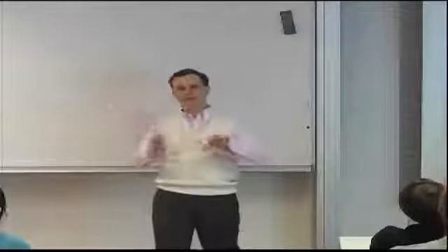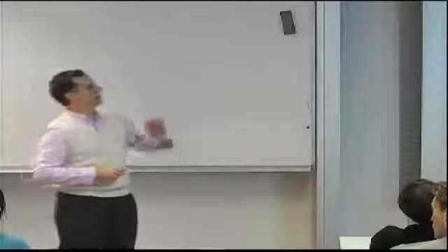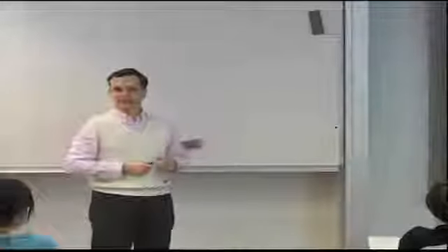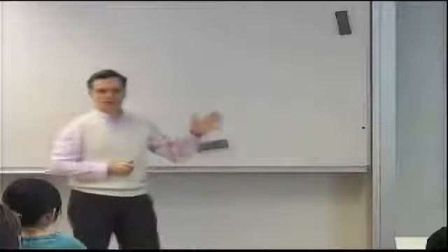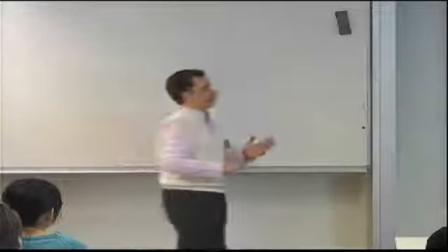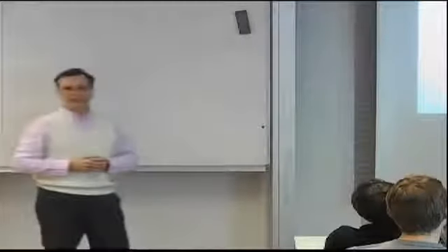That means you may be having also large strains. So indirectly, not just because a large deflection is something we typically avoid, but indirectly this may be related to actual forces and stresses, and therefore this is an indication that a lot of the advantage from panel A has now disappeared.